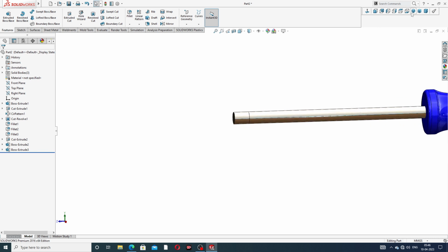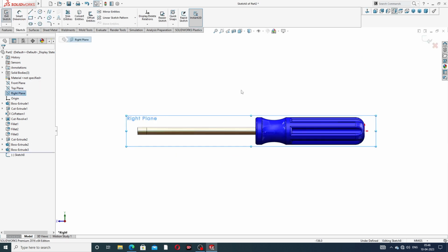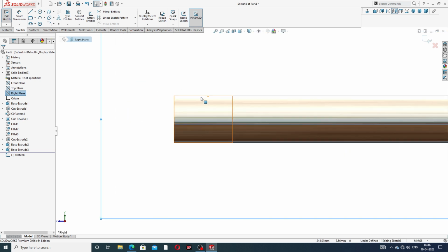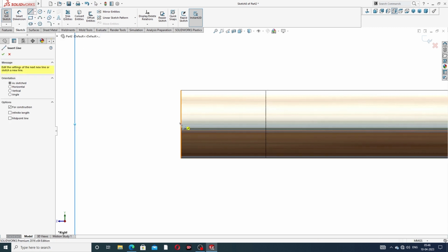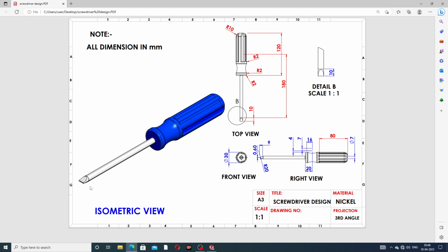and also select the plane, the right plane, and sketch normal, and draw a cutout, use a center line, and the center line connects this point to this, because an important point is the cutout, this is very nice looking here, and this cutout is used here, okay, this is, use a curve, radius is 20 millimeter, and this length is 9 millimeter, and this also distance is 0.6 millimeter, and click OK.